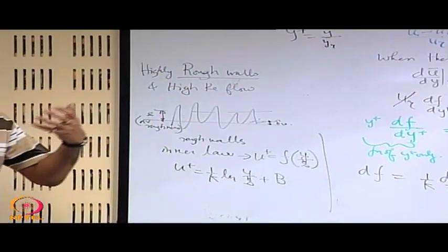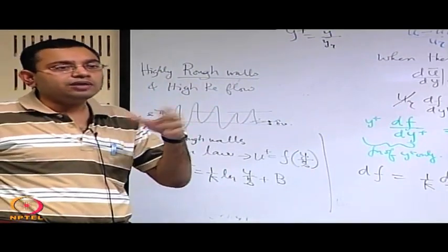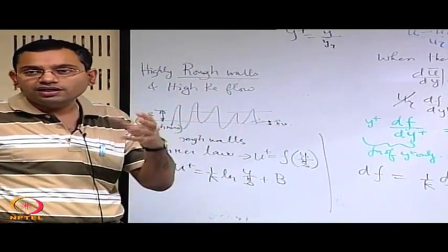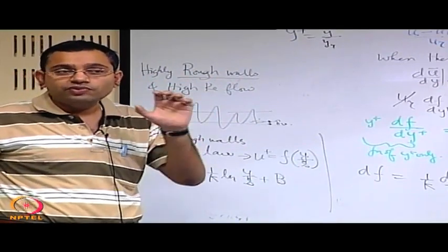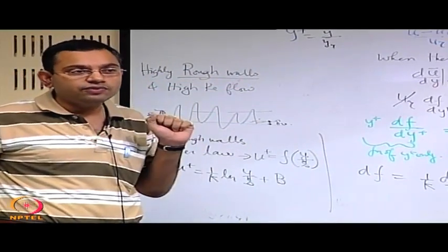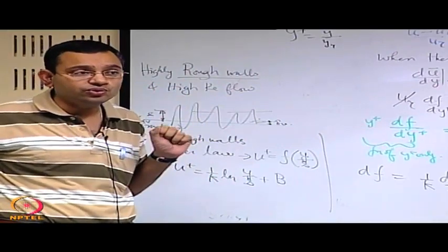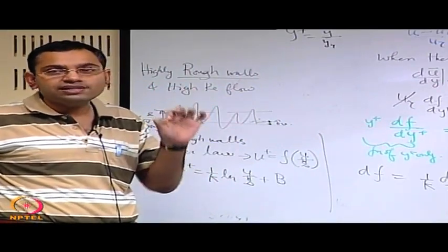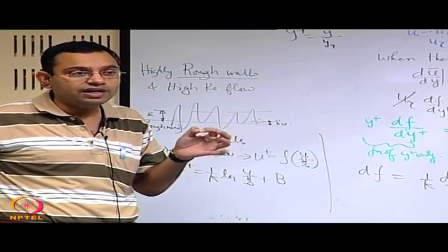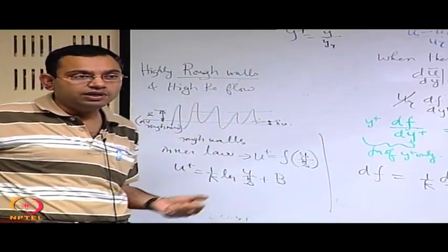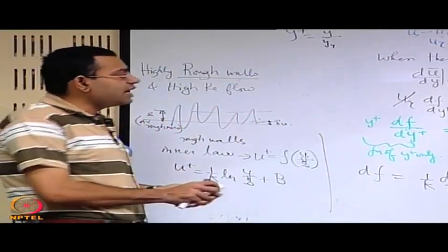We have till now developed a sort of feeling, maybe not by explicit understanding but by intuition, that viscosity dampens out disturbances. So viscosity sort of stabilizes the flow, but this is not always true. I will just briefly talk about an example where viscosity in a turbulent flow destabilizes the flow. That means it instigates the instabilities. Qualitatively it is like this.